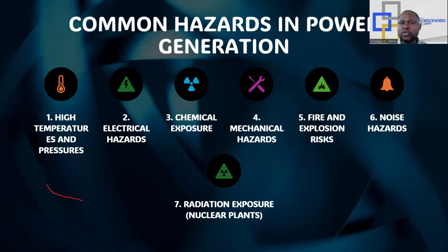So the best thing to do is use hearing protection like earplugs or earmuffs. Implement noise control. I remember I worked in one of the beverage facilities in Ikeja. When I got to the place newly, I noticed that some of their plants were actually noisy. And to be sincere, these people do not use earmuffs. They said it doesn't make them comfortable. Now, I made them see reasons why they need these things. Safety gadgets are not meant to make you comfortable, but they are meant to protect you. So you need these things in order to protect yourself.